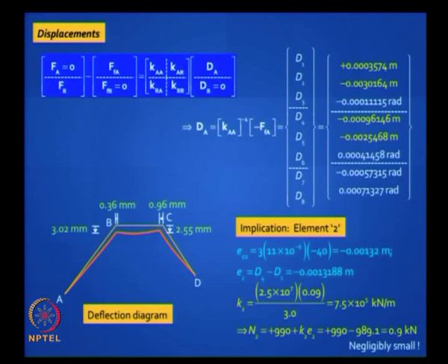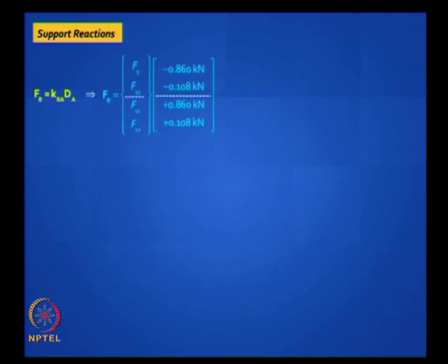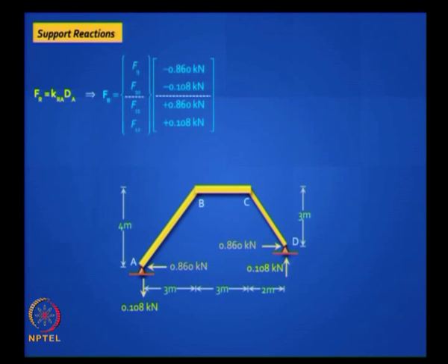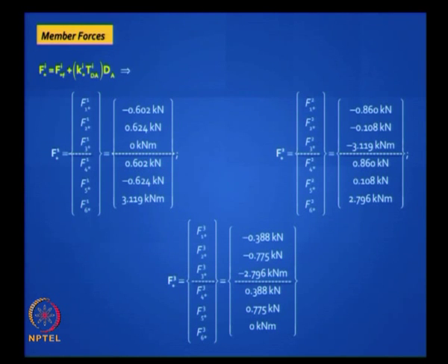The next step is, here you find the value is negligibly small, and you find out the support reactions. The support reactions also turn out to be very small, not surprisingly, and it's self-equilibrating. Look at that. There is no load on the structure, you cooled the structure and you got support reactions. It's just self-equilibrating. There's no external direct loading acting on the structure. You can find the membrane forces. Now you get shear forces and bending moments in addition to axial forces, but they are of small magnitude.